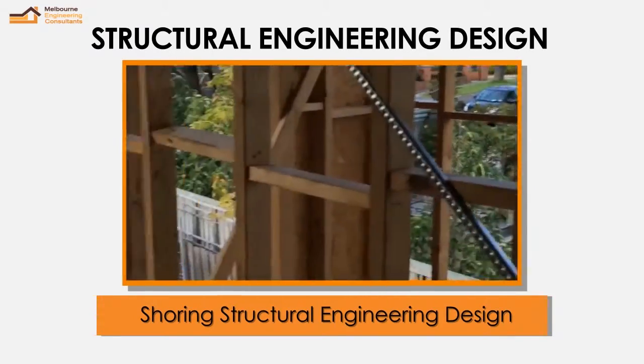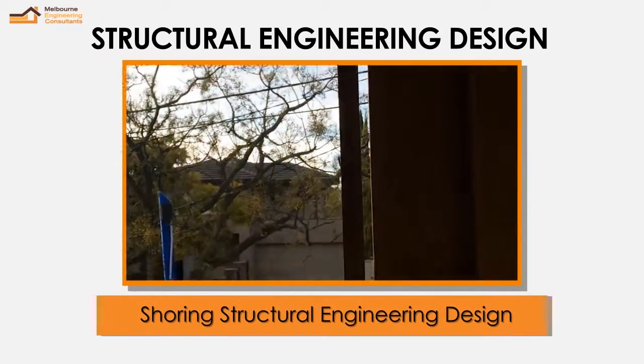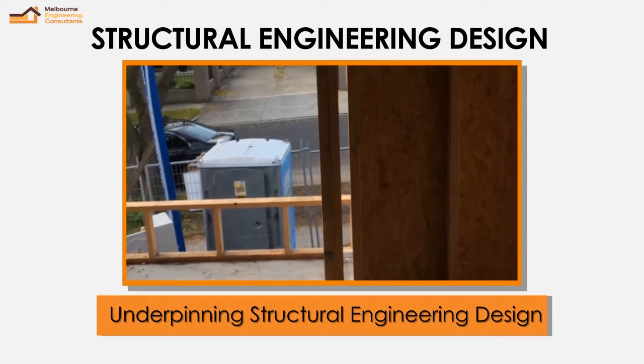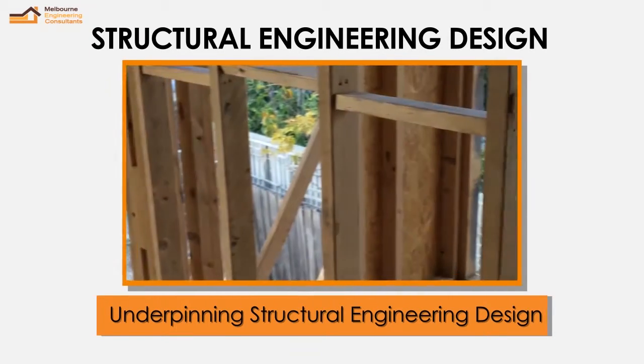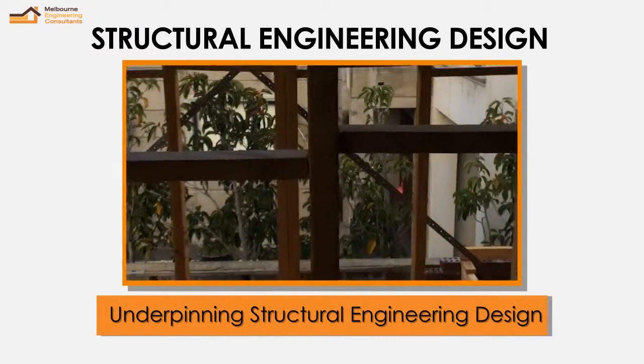Here this is again a lintel at the top we have, and double stud sitting on either end with the hardwood bracing just for the wind brace, and double strap bracing, and cross bracing on the external wall to transfer the wind load.